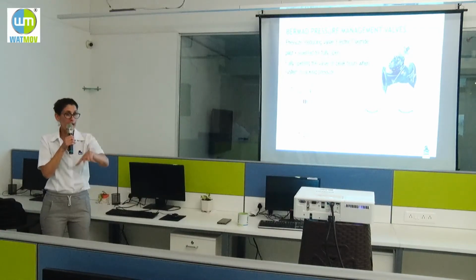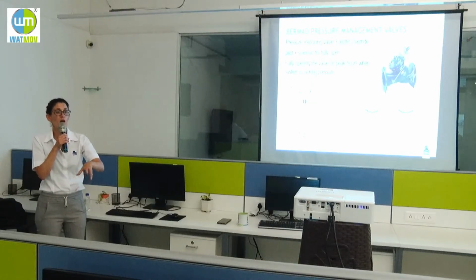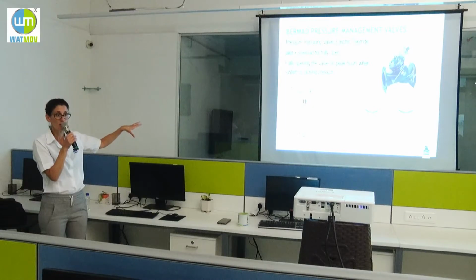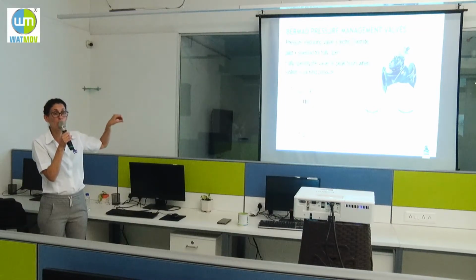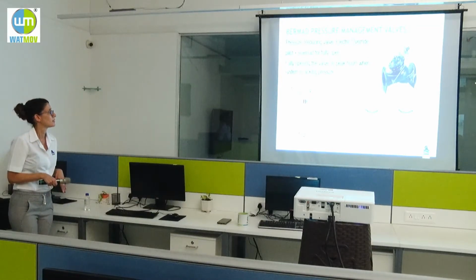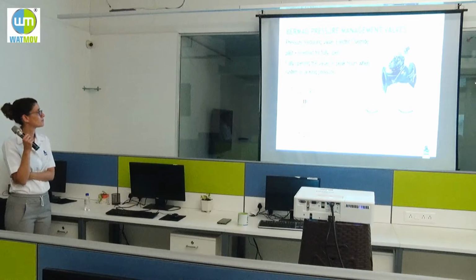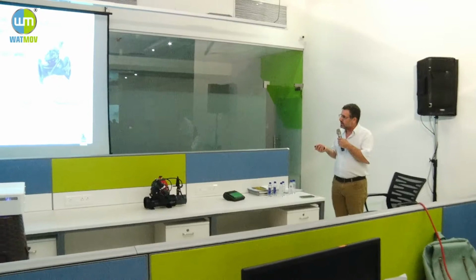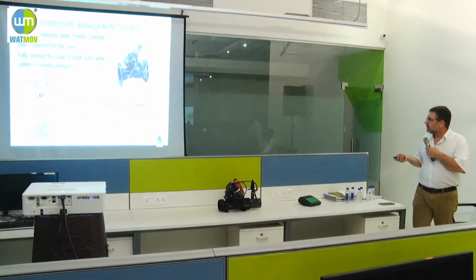When we are going for night hours, for low demand, we de-energize the solenoid, and it will connect back to the control loop and will reduce the pressure with the reducing pilot. So this is good when we have low pressure. In the end we got a graph like that. When the demand is going down, the pressure goes down with it, and when it goes up, of course we give the maximum pressure.